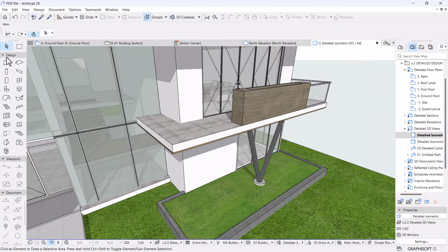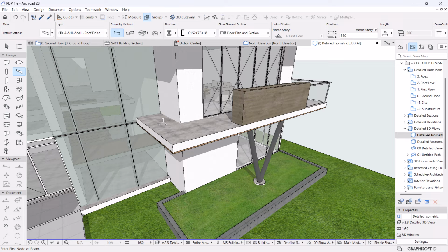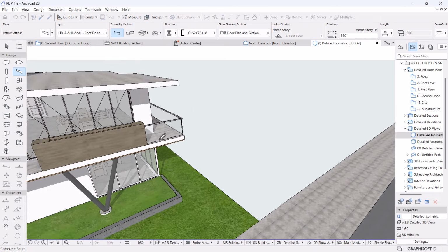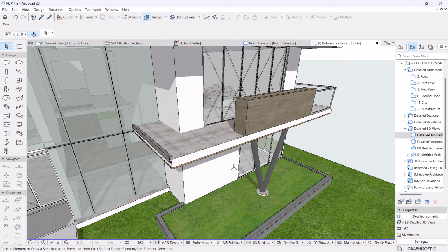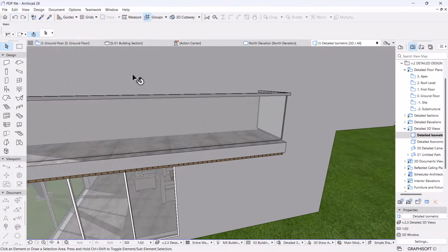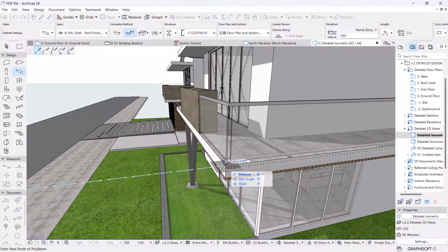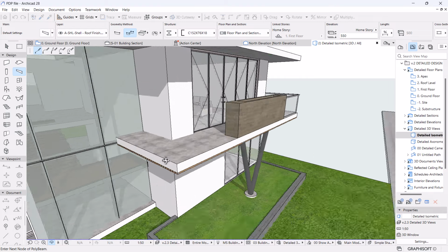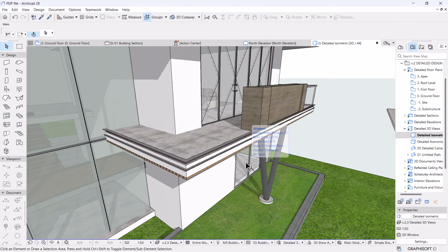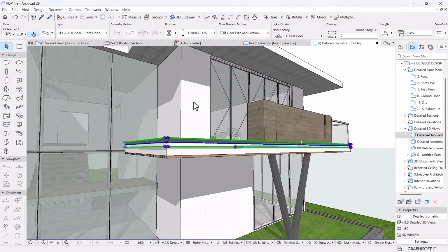Okay, so I'm going to activate the beam tool, change the profile to complex profile. Then I'll start with the 152 one, and then you can just place them on 3D if you are comfortable with doing that. So do this. I'm going to say undo. I'm going to start from this point, activate. I'm going to use the chained geometry method so that I can quickly run the placement of these beams. To that point, right click, hit OK. I think it looks small. What I need to do is to change it to 200. Yeah, this makes sense.